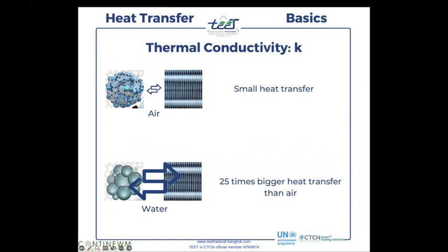That's what I designed with this small arrow of heat. Heat transfer is small when you transfer the heat from air, but when you use water with the same coil, the heat transfer is bigger because of the thermal conductivity that is 25 times bigger in water than in air.